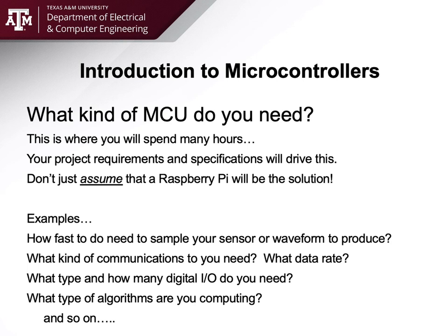And that's the bare minimum. Quite frankly, I always do a 10x rule. So if I have a 10 hertz signal, I always try to put 10 points per major period. So for a 10 hertz signal, I will sample at 100 hertz because at 100 hertz I'll effectively be able to reproduce a good faith estimate of what the signal originally was.